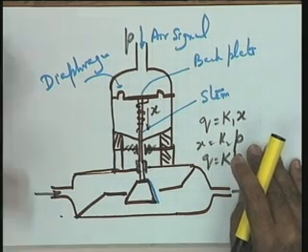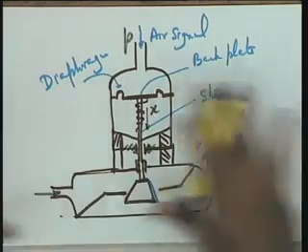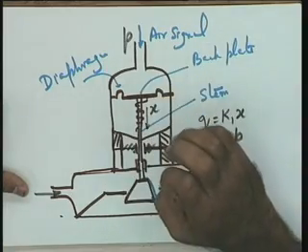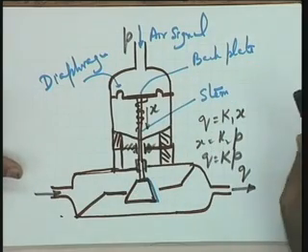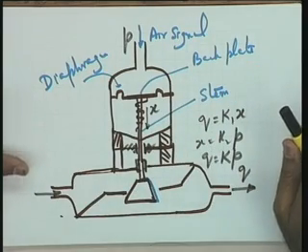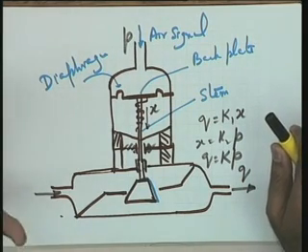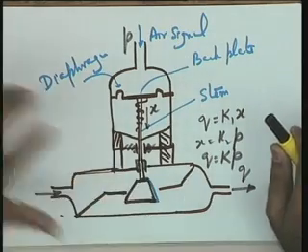Okay. Any other alternative where the power requirement is also met? Please recall your test problem. In the minor test, a problem was given wherein the valve was, instead of a linear motion, a rotary valve. In that case the required power was being given by an electric motor, so it was an electric motor operated valve. The error signal could go to the motor, which generates the appropriate torque, and that torque then operates the valve.